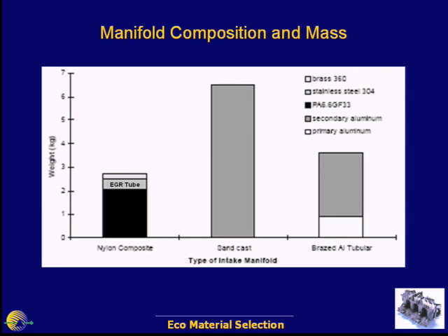Right, in aluminum we had bauxite, again a mineral found in the Earth's crust, rather abundant, still relatively dilute, and we use this high pH precipitation process to get that aluminum out in a very highly pure alumina form, which we then used an electrolysis process to refine, making some CFCs and using a lot of electricity in the process. That was a primary aluminum. Virgin aluminum is how I referred to it. Recycled aluminum is melted scrap aluminum.